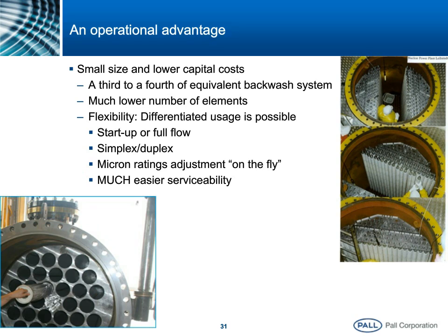We've had instances where these filters can be used with a very fine filter during startup and coarser during regular operation, where we expect the contamination to be a lot more stable and the water to be a lot cleaner, for example. And you can see on the right side what it takes to change elements in a large backwash system. Somebody is actually inside the vessel changing hundreds of elements, as opposed to only having to pull these horizontal elements from the outside.